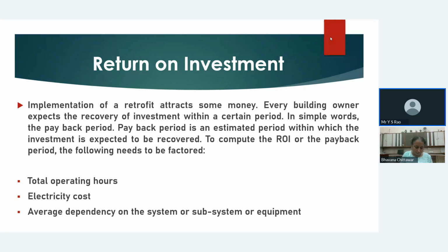The time period that is needed to recover that investment by the implementation of the energy conservation measure is the payback period, usually calculated on the basis of several considerations like the number of hours the system operates throughout the year, electricity tariff, and dependency of the user on the upgraded system.